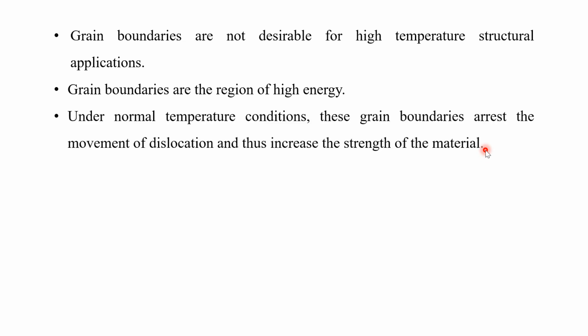So, grain boundaries are therefore not desirable for high temperature structural applications. I've already mentioned they are regions of high energy. As temperature increases, they will start becoming mobile, they will slide past one another, and as a result, they will propagate the dislocation or they'll start cracking.